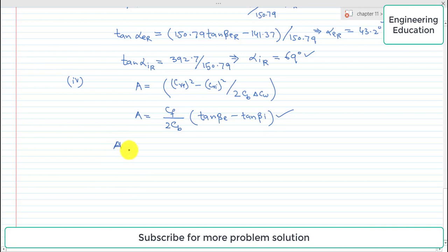Degree of reaction at tip is equal to CF value 150.79 divided by 2 into the blade velocity at tip, 235.62 meter per second, into tangent beta ET, 64.8 degree, minus tangent beta IT, value is 0 degree. So simplifying this, we get the degree of reaction value, which is 0.68, and this is the degree of reaction at the tip.